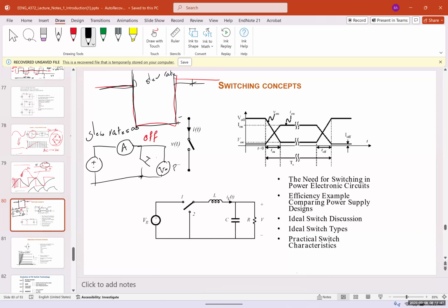Perfect. So the voltmeter, what is the internal resistance of a voltmeter? It's infinite. So technically it's like an open circuit, yes? For an ideal voltmeter. You learned this in measurements and instrumentation. So if this is an open circuit and this is an open circuit, then this voltage, because these are in parallel, would be equal to the voltage of the source.